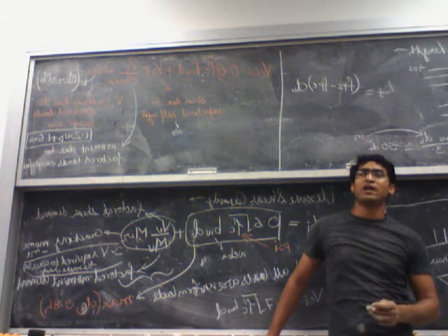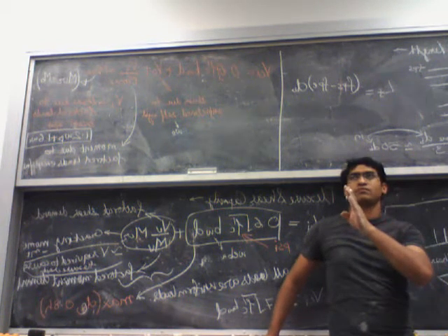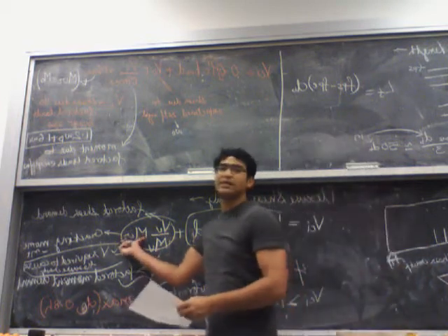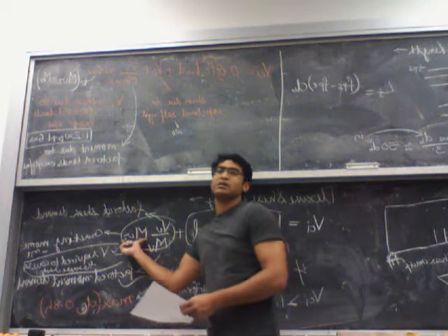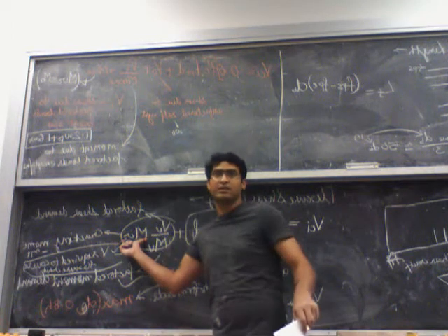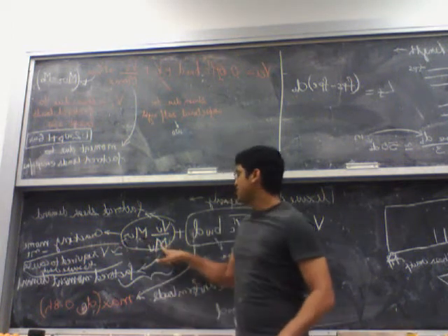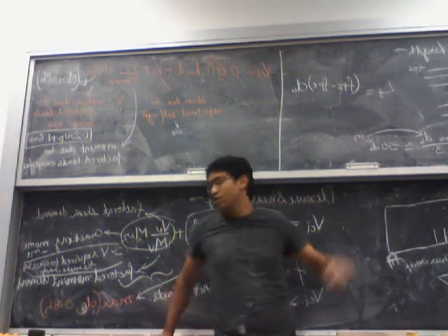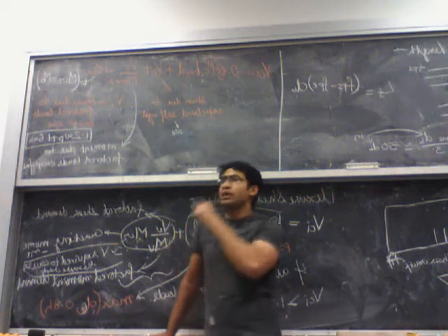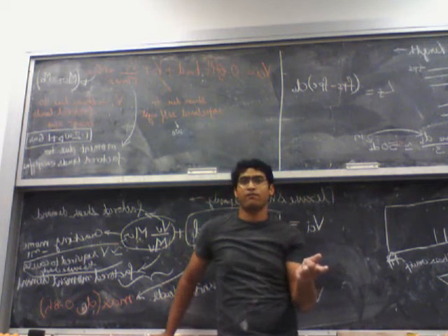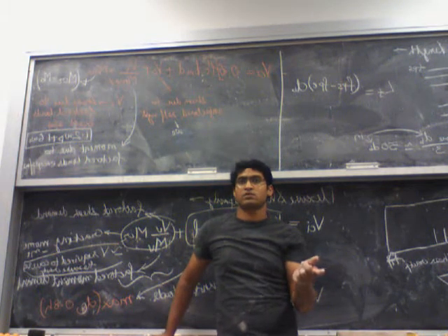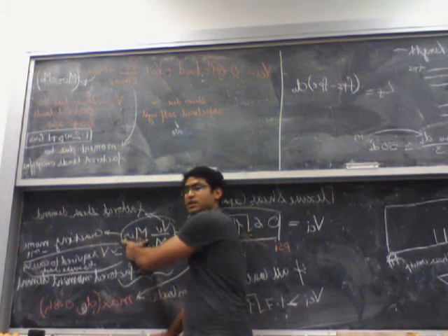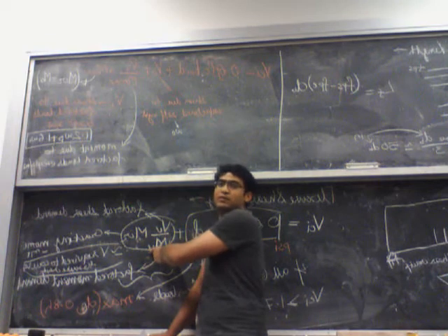And I think they are trying to relate it to the demand, because this is your capacity, right? Your MCR is the capacity before which it actually cracks. And this Mu and this Vu are directly related to each other, since the values of Vu and Mu will depend on what kind of loads you have. So it's just trying to convert this capacity, which is currently a flexure capacity, into a corresponding shear capacity.